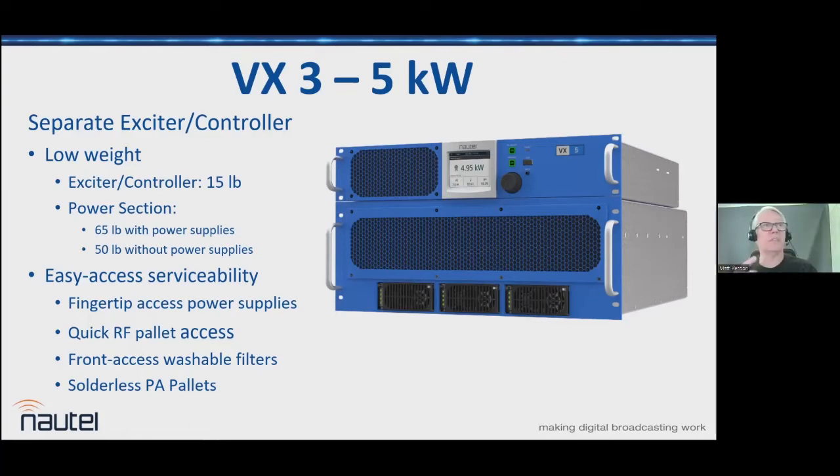While we're talking about fans, it's also worth noting that the reason we put the fans at the front, which obviously creates the noise in the first place, is because we're pulling cold air over the fan bearings and the fan housing, and so we're pushing cold filtered air over the electronics, including the fans themselves. That gives us much better longevity for the fans and cleaner air for the components inside the box. We believe strongly that this is a very good design, as it means you get fewer fan failures.